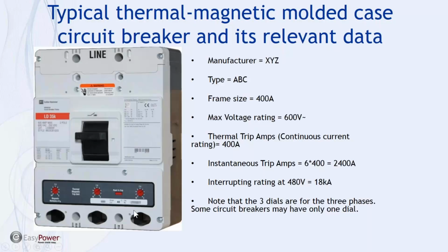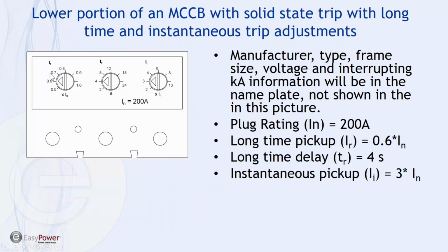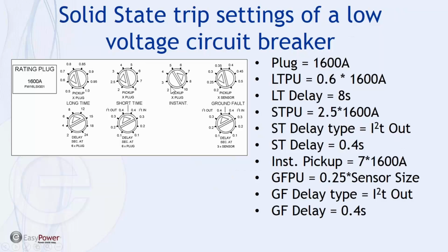And a good image of these dial settings, which are the trip settings, is important, and each of these dial settings will have a bearing on the time to quench an arc. So whether you record the symbol or whether you record the number, it is greatly advisable that the details and accuracy be as complete as possible.